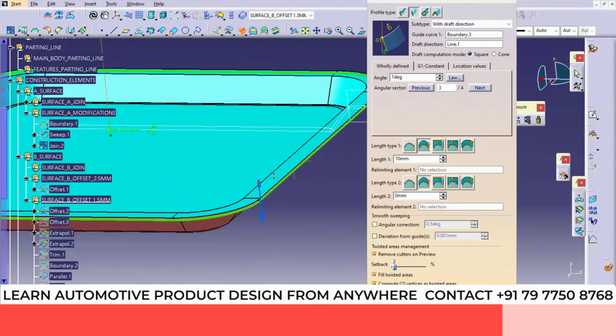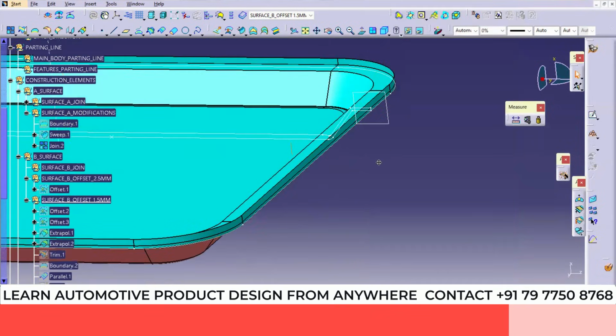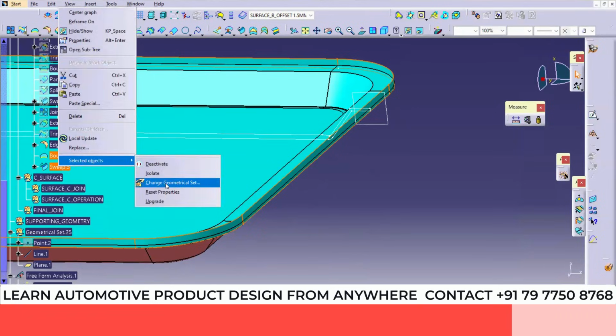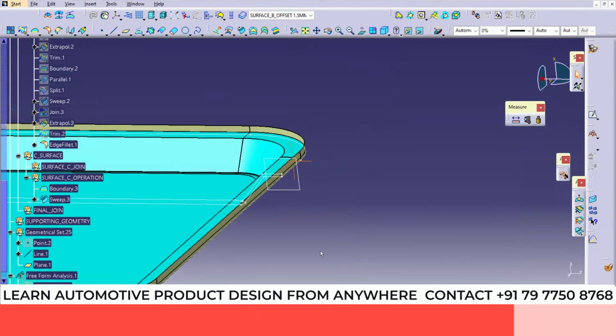Okay. And which side arrow direction? Select 10 degree first. You can select the arrow direction, this side or this side. Okay. First I'll select inside 1 degree. Length will be 5 mm is sufficient. Okay. This will go into the C surface. Change geometrical set to the C surface operations. Okay. And now cut the section and check if it is matching or not.